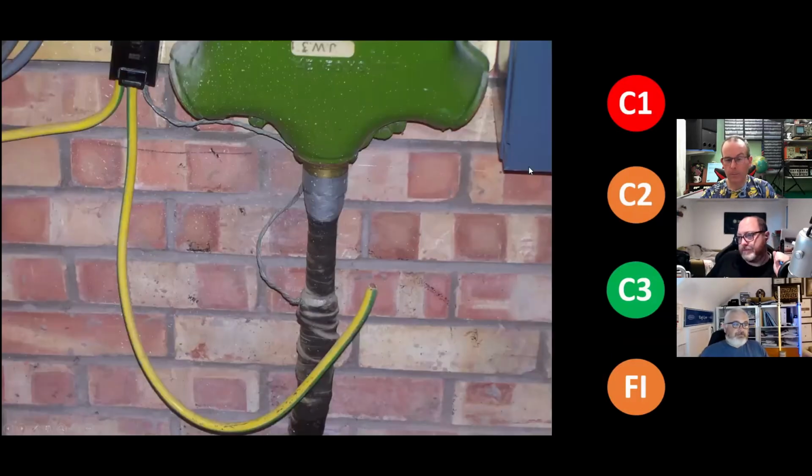Here's another one. Okay. Interesting. Again, a metal cutout, looks like it's a JW3 if you turn your head upside down. Which is a weird one. One of John Ward's old ones, maybe. No, this is lovely, beautiful vintage colour. Three-phase supply and neutral. Decent, chunky, looks probably like a 35 mil conductor there.